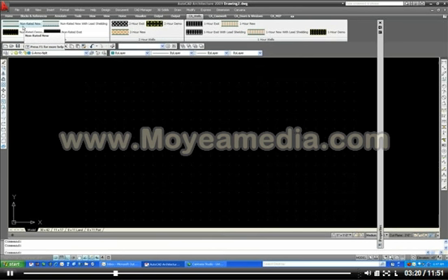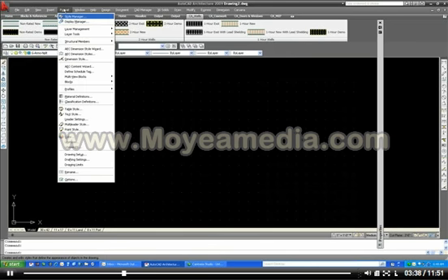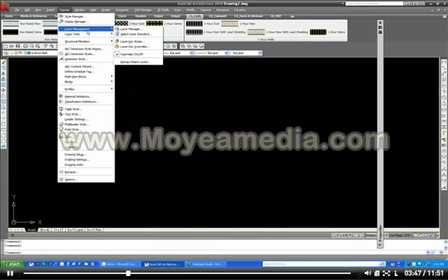One important key issue with these wall styles is you want to make sure that you're using your layer key style overrides. The way the key styles work is, whichever wall type you're using, whether it's a new or existing wall style, you want to make sure that your key style is set. So I'm going to go up to the Format pull down menu at the top, not File, and select Layer Management, and over here is where you set the key override.